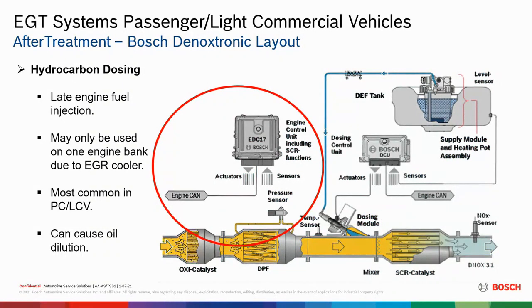Medium heavy duty, done with a separate injector right in front of the DOC. The problem with this is it causes oil dilution. I mentioned that at the beginning. So service intervals need to be monitored very, very closely, especially if we're doing a lot of regenerations. And this is another problem that happens as well.